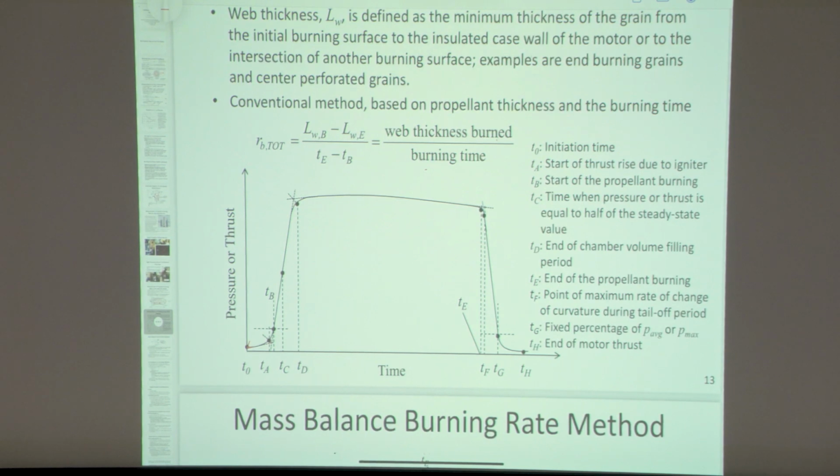So I'm going to start raising the pressure a little bit up here and add pressure to the cylinder inside the chamber. Then all of a sudden, the propellant grain is going to ignite, okay? And then it's going to basically fill the chamber until it becomes choked. And then at that one point, depending on the grain design, I could potentially have, and this is what you'd want in these measurements, what's referred to as a neutral burn, so that the pressure doesn't change as a function of time until I burn out the web thickness.